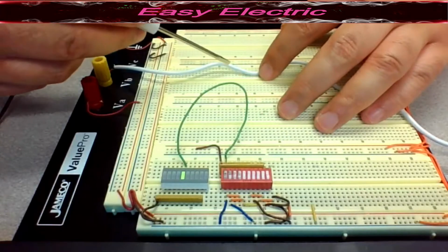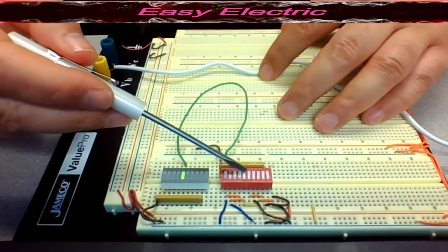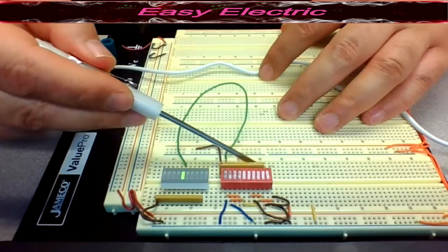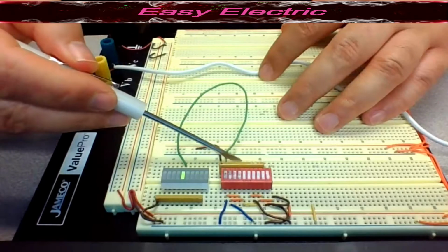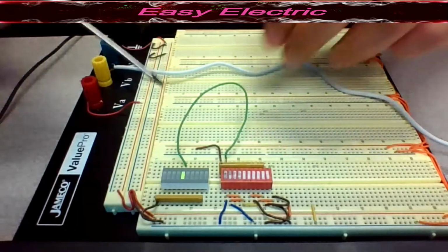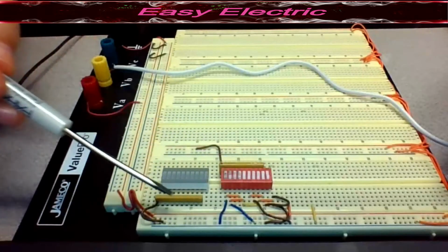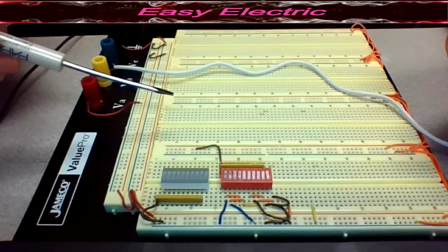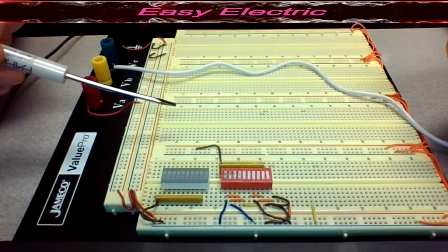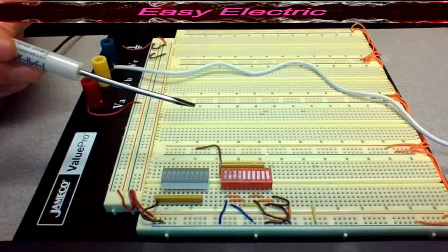Whenever we need to check the outputs, we use these LEDs. If we need to put in some input 0 or 1, we use these inputs that we have and give the 0 or 1 based on the needs that we have. So for this project, we just want to see how we could make this workbench, keep it in one corner of our breadboard, and use it as a test bench.